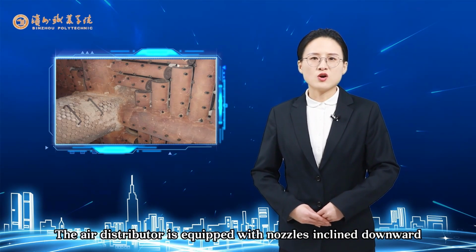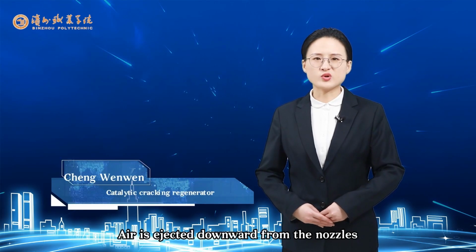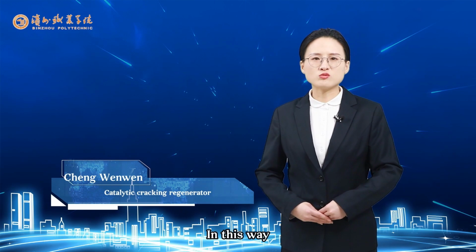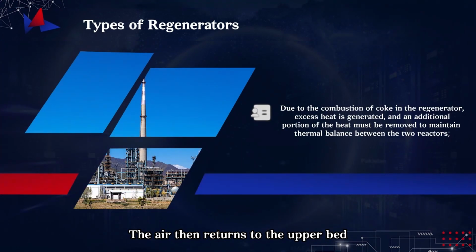The air distributor is equipped with nozzles inclined downward at 45 degrees. Air is ejected downward from the nozzles. In this way, catalyst cannot enter the distribution pipes. The air then returns to the upper bed.